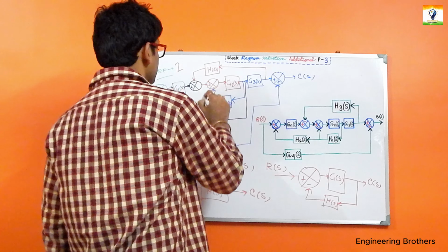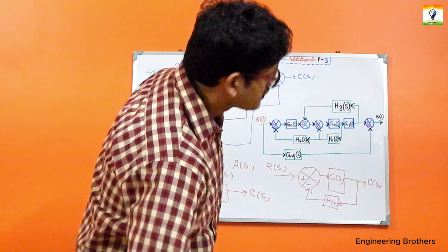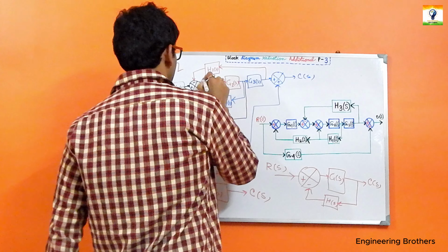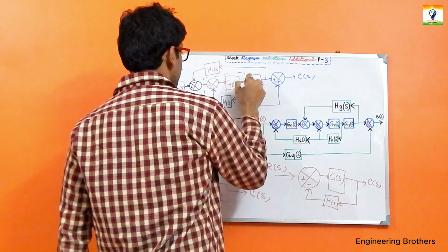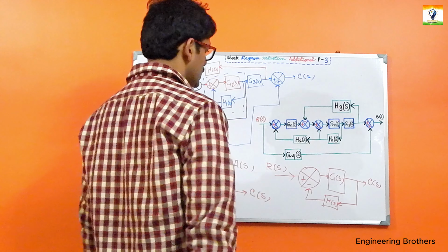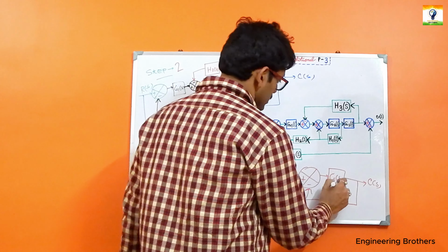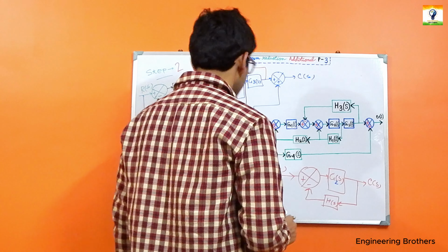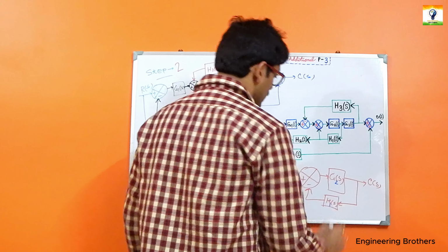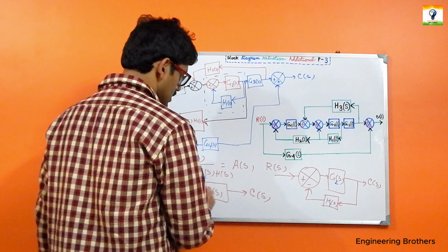Now this is the formulation that we are going to follow over here. Now consider this inner portion of a block over here. Consider this path over here. We are going to apply this formulation in this given block, and quite naturally if we change this gain block to our G2S, and this one is going to be our H1S for this inner block, the formulation will be: this one is our G2S and this one is our G2S H1S.